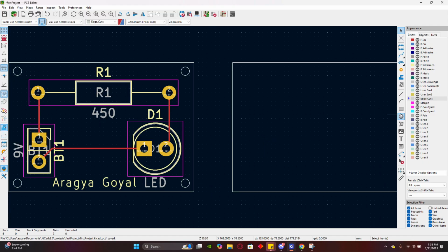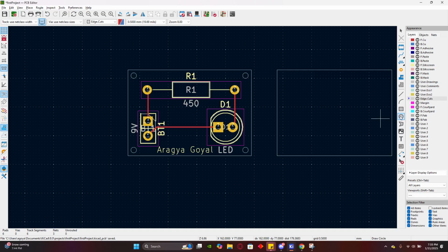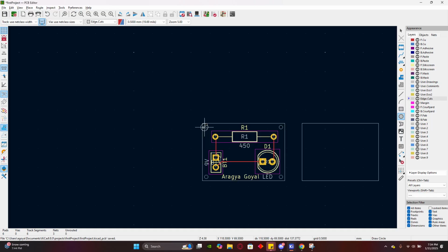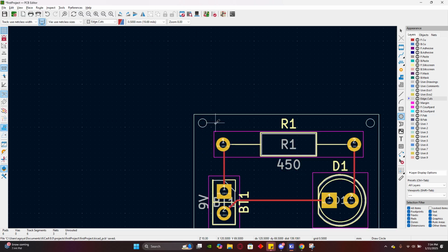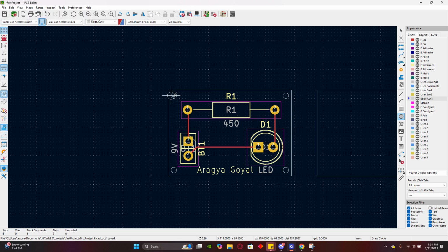So basically for that, you'll just use the whole thing right underneath the rectangle option for a circle one. You can place that anywhere and then change the radius. I think I just went with 0.5 millimeter holes, but depending on what your project is and how you're mounting it, you can change how much you want there. Once you have those, you put them in the 4 different corners.